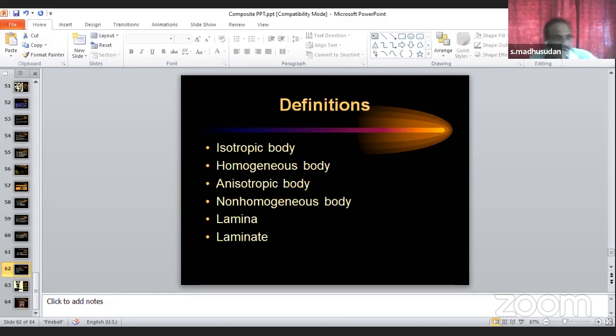Apart from these valuable inputs, how can you overcome the particle size or shape or location of the particle when you stir in the matrix? This is very difficult. If you publish a paper, the first thing they ask is how you avoid the agglomeration problem in your matrix. Even if you take a microstructure after fabrication, you can't avoid this agglomeration problem completely. That will be there, but it should be minimum, not maximum.